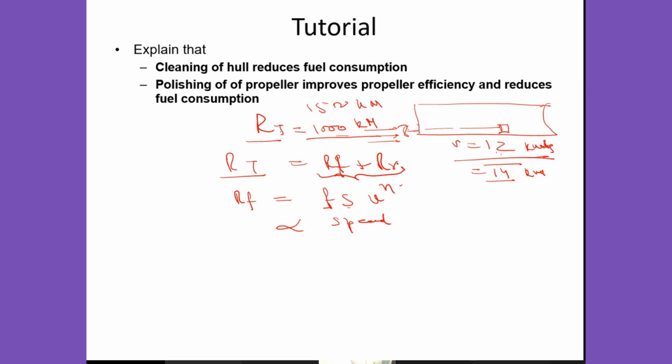I will come to RR. That is where your question will be answered, because you are saying a bulbous bow. Now, with the introduction of the bulbous bow, we'll see what the effect of that is. So first of all, the first component, frictional resistance, is proportional to speed, proportional to the length of the vessel, proportional to S, the wetted surface area, the underwater area, in square meters, of course. And proportional to the roughness of the hull.